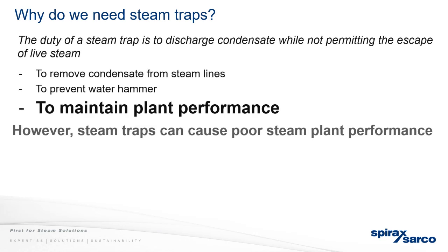But if you do not look after them, they can cause poor steam plant performance by making your steam wetter. There's more carryover in the pipe and more corrosion in the pipe. So they are, like I said, integral to the steam system.